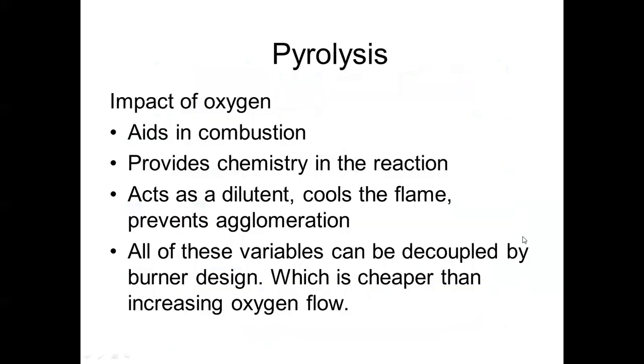within these burners. So the impact, if we look at oxygen and what it does for us, it certainly aids in the combustion of this process. It certainly provides chemistry in the reaction, and it could also add a tremendous amount of oxygen in there, more than can be used in the combustion process. It'll act as a diluent and it actually cools the flame down, because at an excess amount it will not be able to participate and have time to participate within the process. So it's going to cool the flame. It'll make more agglomerates than aggregates, and that's potentially bad.